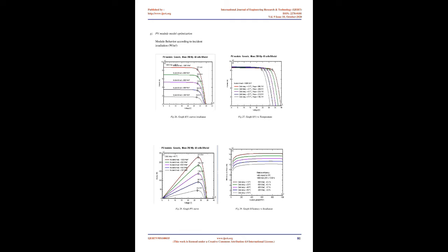E. Secondary parameters. μISC, often named alpha, is specified on the main page of the parameters, and used as such in the model. For crystalline modules, its value lies usually between 0.04 and 0.08%/°C. Specified μVOC, 127 mV/°C. Absorption coefficient for temperature. Absorptivity coefficient, alpha, 0.9. This is the irradiance global absorption coefficient involved in the thermal balance for determination of the array temperature.